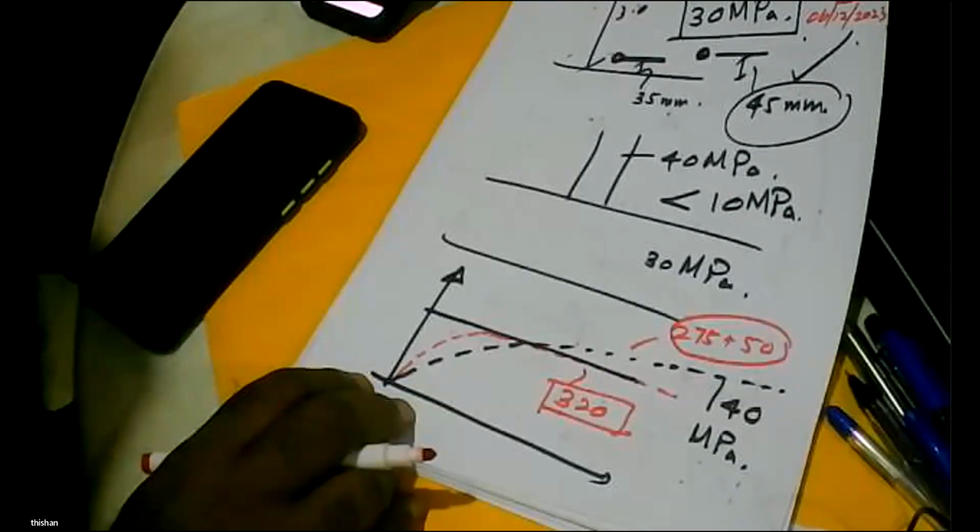By that time, it's a 50-story building, 30 floors have been completed, and by the time the second year goes, all the floors are completed. By the time the maximum dead load comes on, the raft is not a 30 megapascal raft, though you designed it as 30 megapascal in 28 days.